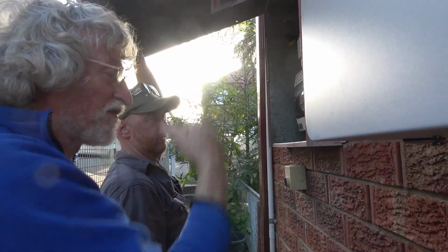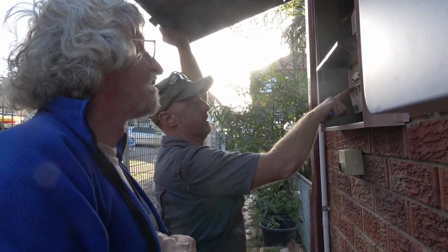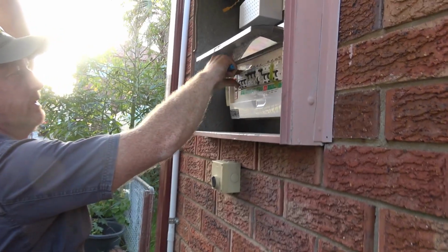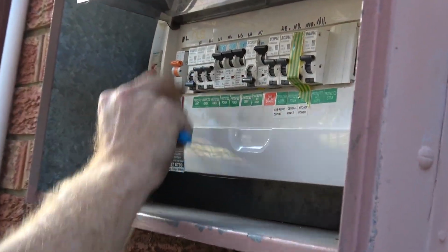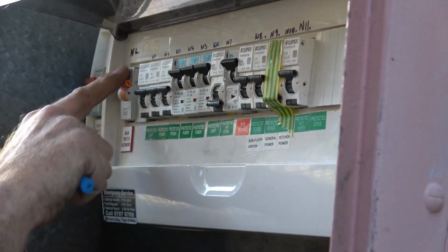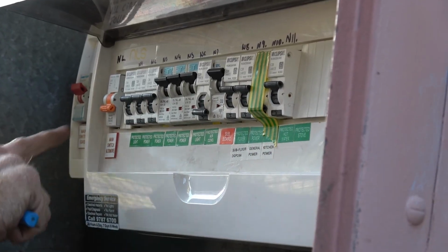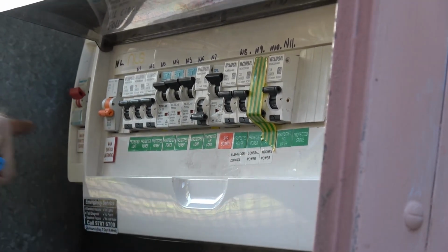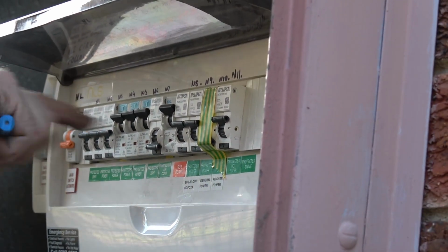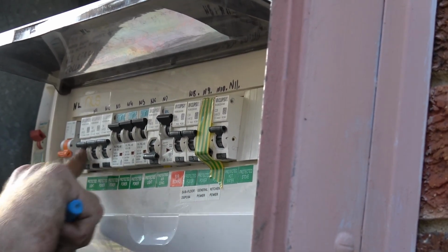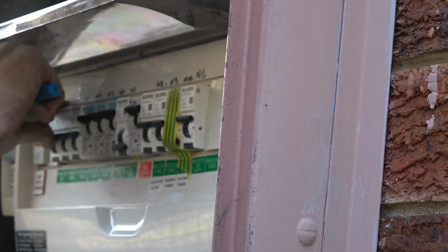That one will turn off the grid input. Yeah, and if you turn that off, see there's power in that now, right? But if you turn that switch off, there's still power there. Yep. But then if you turn this switch off, there's no power there, because that switch is controlling those. Under normal circumstances, it comes into this one, goes down, comes back into this one and goes through that. So it's always going through this, no matter what mode it's in. Yep. So if you turn that one off, that would kill all your circuits. Yep. Yeah, power's back on now.